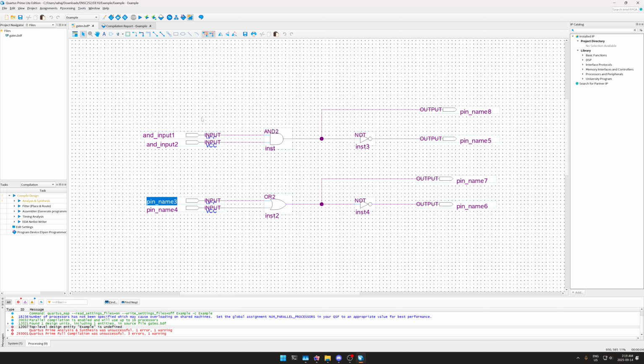And that's because these are names, as you can see, and2 is all caps, are reserved names. So let's restrain ourselves from using these. So I'm just gonna go ahead and do OR_input1, because it does cause conflict when synthesizing.